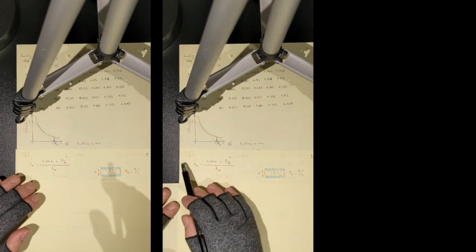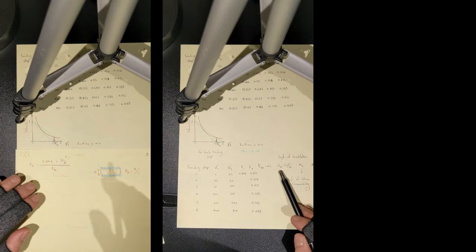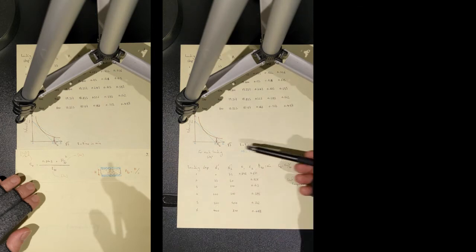So you can see that C sub V can be easily determined directly from a one-dimensional oedometer test, and it can be reported here, C sub V in centimeter square over hour. You can see that for each loading step, you've got a certain value of C sub V. The next important parameter that you can determine from an oedometer test is M sub V. This is coefficient of volume compressibility.